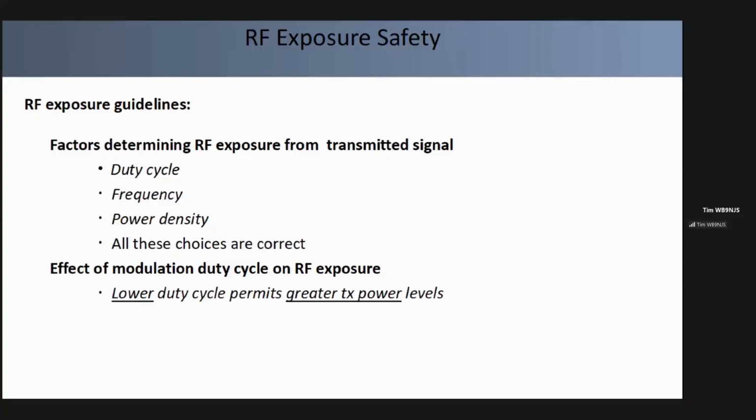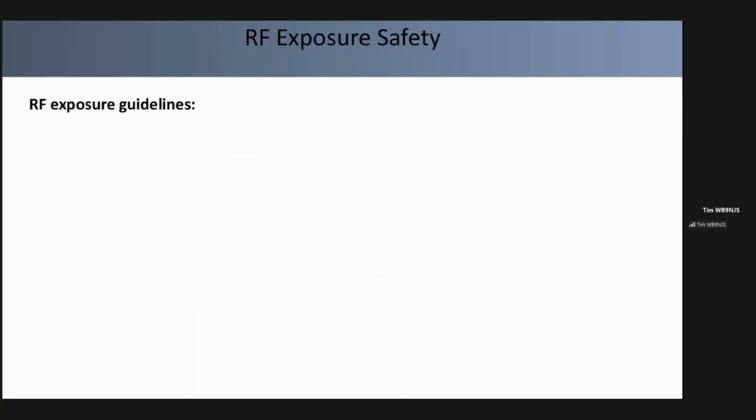Something like single sideband has a fairly low modulation duty cycle. There's a table in the study guide that lets you compare modulation duty cycle. A lot of digital modes and FM are going to be a very high modulation duty cycle. But the answer to the question: lower duty cycle permits greater transmit power levels.